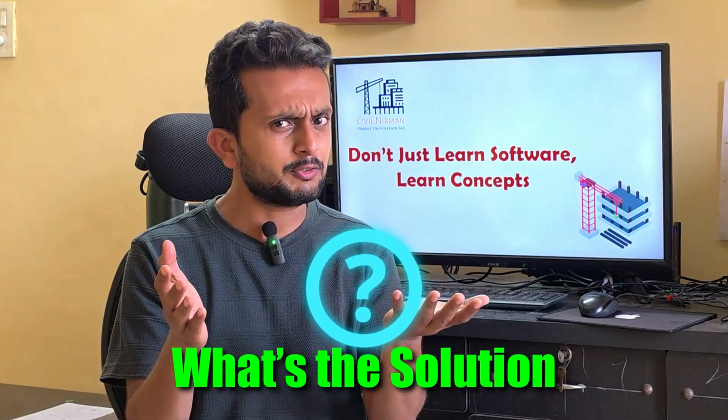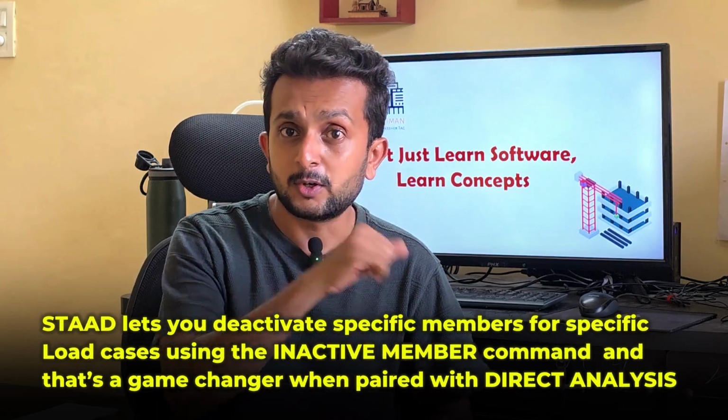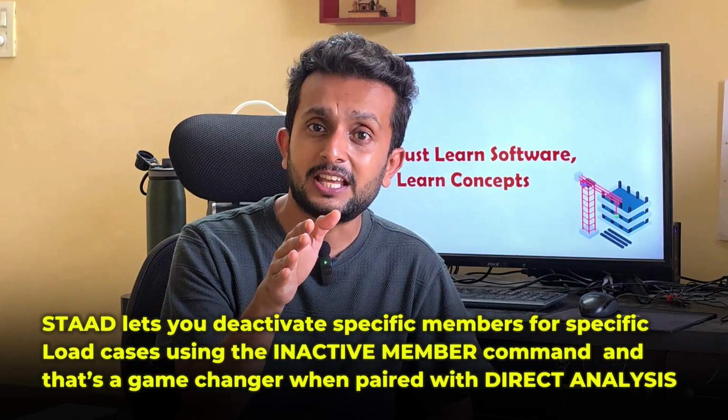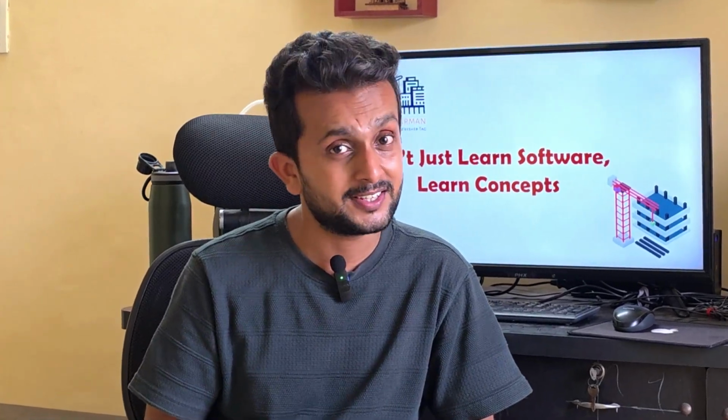So what is the solution for that? To solve this, STAAD lets you deactivate specific members for specific load cases using the inactive member command, and that's a game changer when paired with direct analysis. So let's check this out with the STAAD model with example.